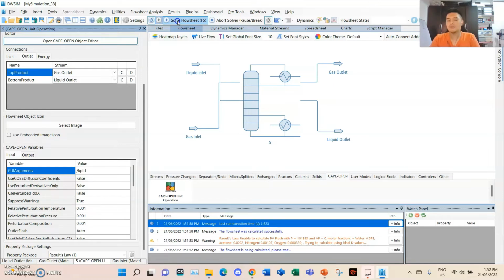So the NRTL compared to the Raoult's law, NRTL uses a more realistic approach in simulating real-life procedures of different chemical components. But in order to fully solve this problem, we'll just use Raoult's law, which is more ideal than real compared to NRTL. But it can still give a good estimate of what we will be expecting as value or output based on the given conditions in the problem.